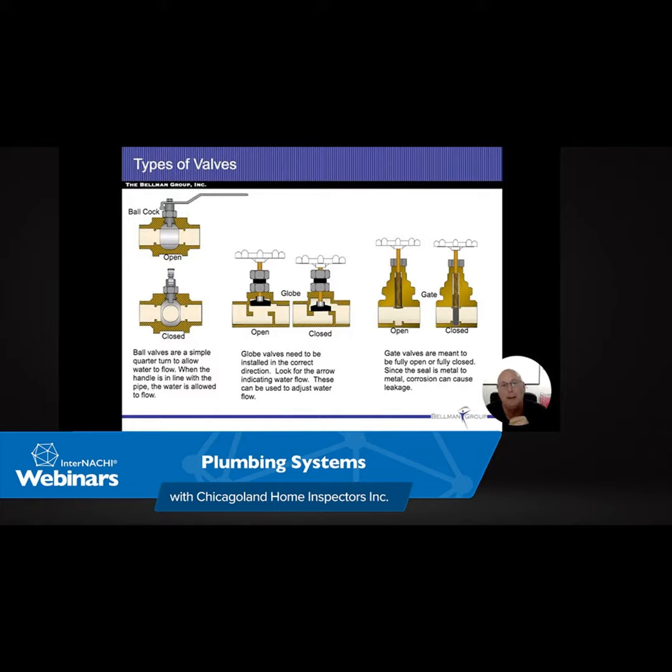All right. The diameter, and this one is a little bit of a math problem. I actually found this really interesting, and I had to throw out the old BS flag when it was first explained to me. I'm like, there's no way. But you take a 1/2 inch pipe, and they're comparing it to a 3/4 inch pipe. And this slide is showing that a 3/4 inch pipe is actually twice as big as the 1/2 inch pipe, even though it's only 1/4 of an inch bigger.